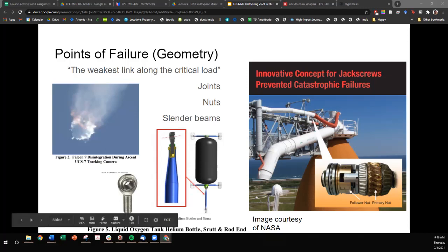If not inspected and replaced after excessive wear, the nut eventually failed. Kennedy Space Center's fail-safe concept for machine jack screws incorporated a redundant follower nut that would begin to bear the axial jack load on the failure of the primary nut. Unlike the case of a conventional jack screw, it was not necessary to relieve the load to measure axial play or disassemble the nut from the threaded shaft to inspect the nut for wear.